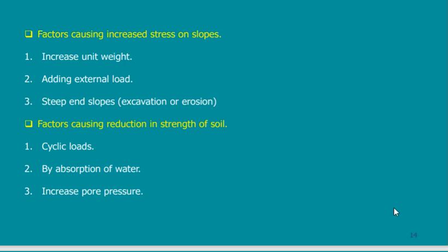And we can say in this case, suppose that the soil is not one layer. Suppose it is multi-layer and each layer has its own C and phi. Then in this case I will have to calculate the C and phi of each layer and introduce it in my calculation. So of course if you have weak layers, then it will affect the stability.